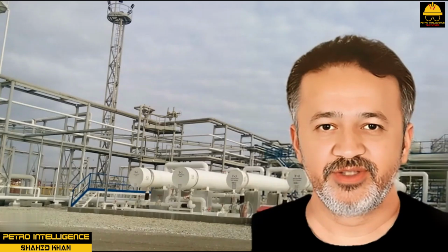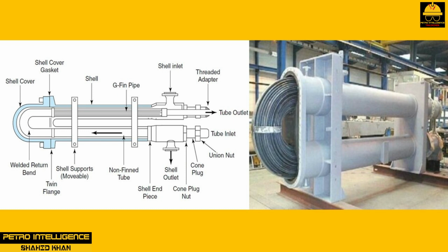Hairpin heat exchangers. The chemical processing industry commonly uses hairpin heat exchangers as shown in the picture. Hairpin exchangers use two basic modes, double pipe and multi-pipe design. Hairpins are typically rated at 500 psig shell side and 5000 psig tube side. The exchanger takes its name from its unusual hairpin shape.